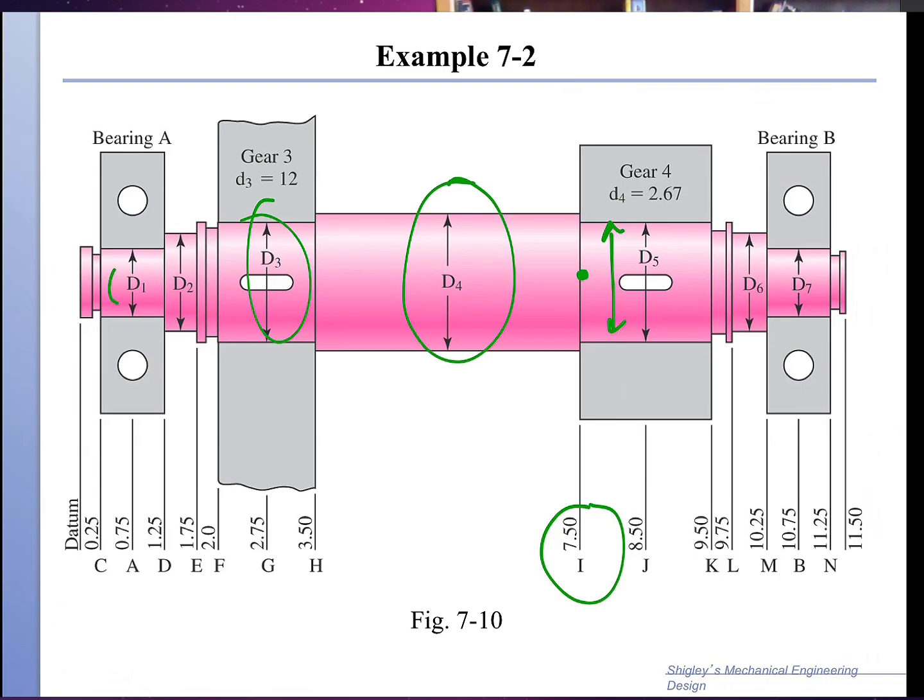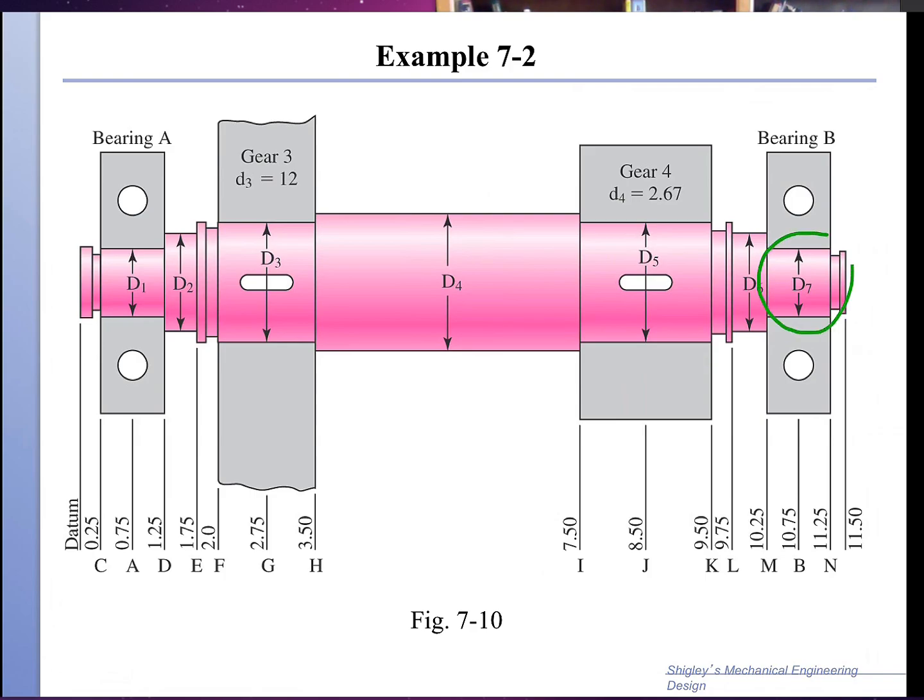What about this? What about that? And so forth. So in order for us to proceed, we pinned one diameter only. So we're going to use some rules for shaft design in stepping the shafts. Well, one of the rules is that since this is 1 and 1.625, then we can take the diameter D7 and D1 to be smaller to fit the ball bearings, and those could be selected as approximately 1 inch diameter.